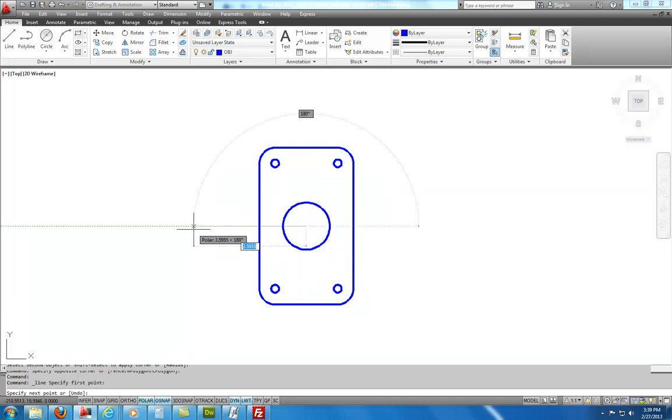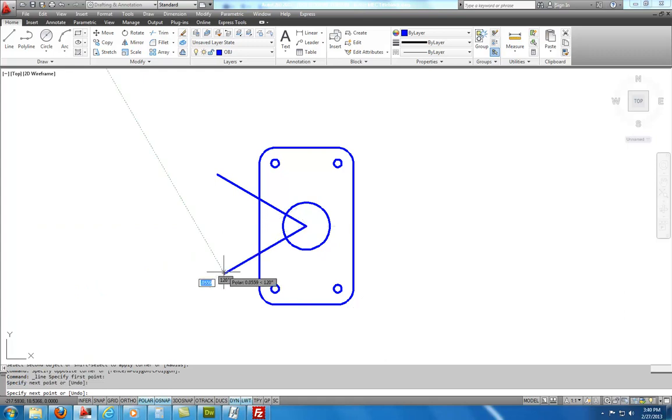If I bring this out 180 degrees, it's a 60 degree opening, and so I'll take 30 degrees from that, and so I'll track this up till it says 150, and I'll get a green track line, and I can draw it at any length like that. That's left mouse button. I'll hit escape, line from this point here, bring it over, bring it down, track until I get 210. Click, hit escape, and now we'll trim.